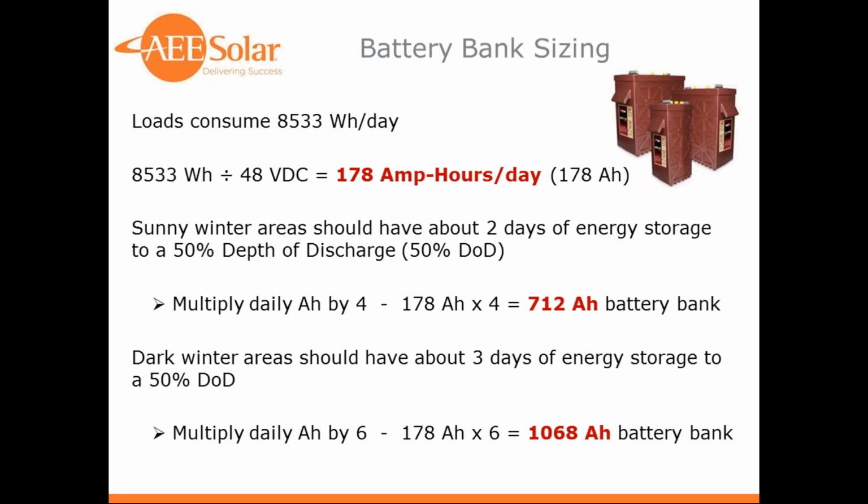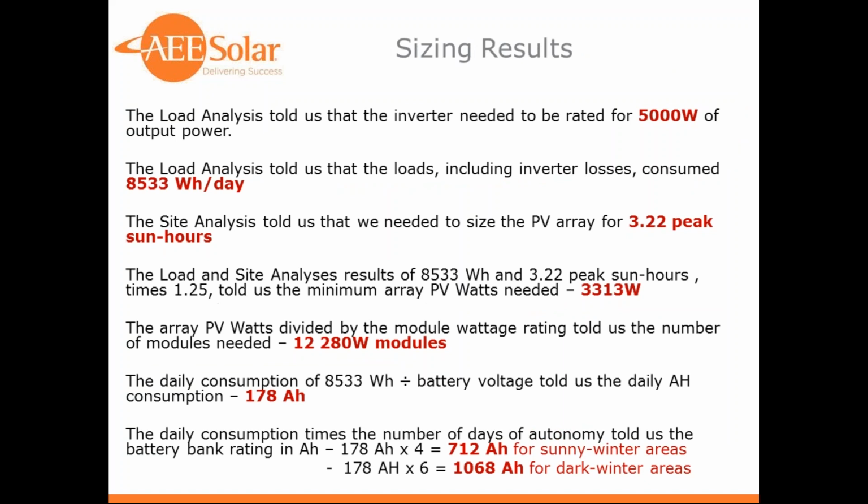So here's kind of the results of doing all that. Load analysis told us that the inverter needed to be rated for 5,000 watts of output power. Again, a 4,000 watt inverter might be okay in this situation, assuming that people could load manage, not run too many loads at once.